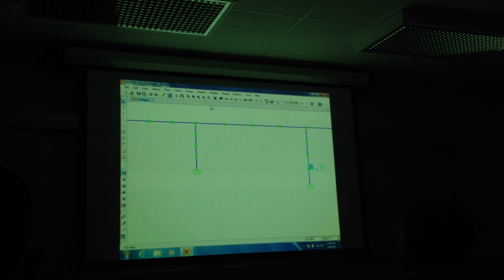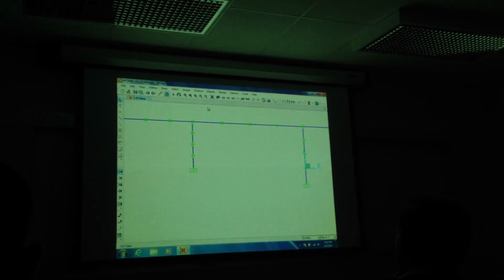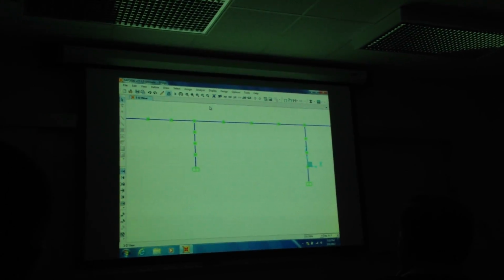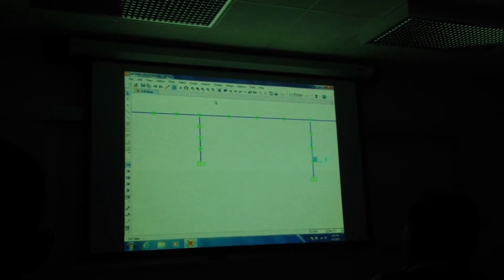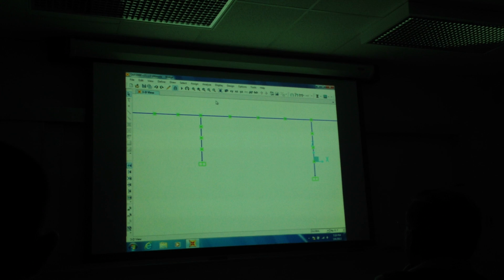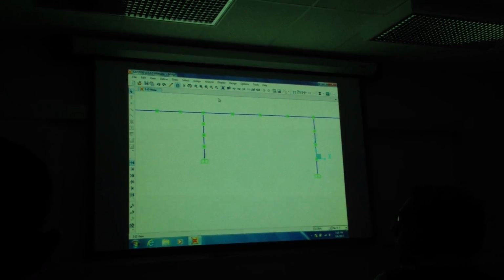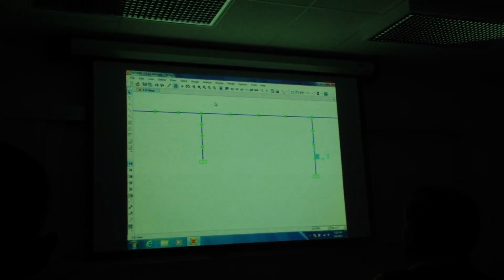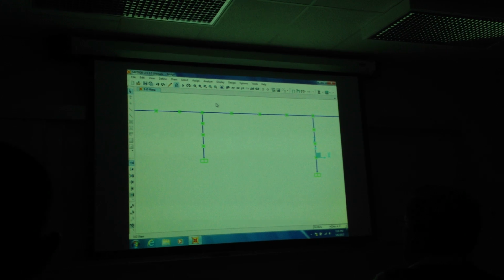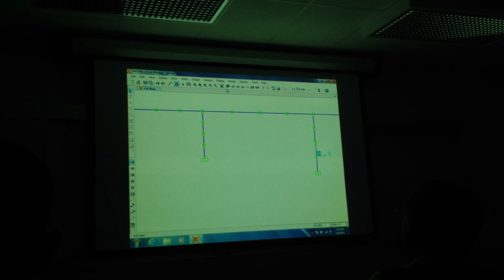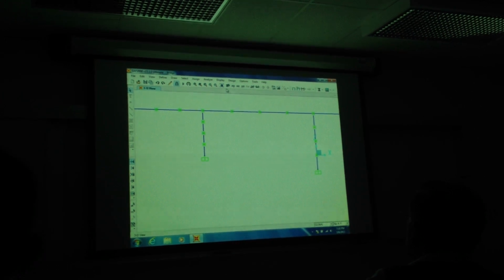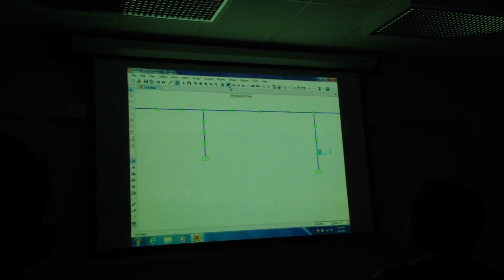What we want to do is create an ARS curve. We developed a design type envelope response spectrum curve last time. I want to find out what is the actual acceleration response spectrum curve, the ARS curve, for this particular earthquake, and then SAP can generate it for you. The earthquake's already in here, right? We gave it the function file, and we already ran it.